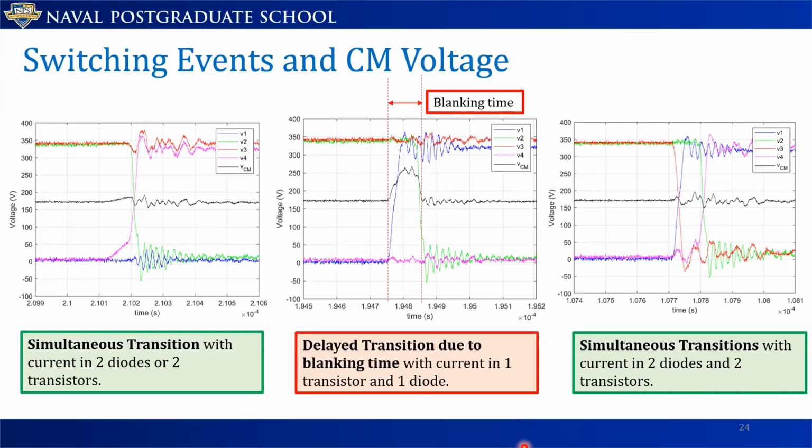In the theoretical calculation, the losses with the silicon carbide devices are comparable to the losses with the regular silicon devices on a pulse width modulated converter. But more investigation is needed. We think that it has real potential for having the same overall efficiency. So comparing apples to apples, a three-phase inverter with PWM and silicon devices against the three-phase four-leg converter with PDM and silicon carbide or GaN devices, we think that we should be able to reach the same efficiency. But that is something for future research, hopefully, some future collaborations.